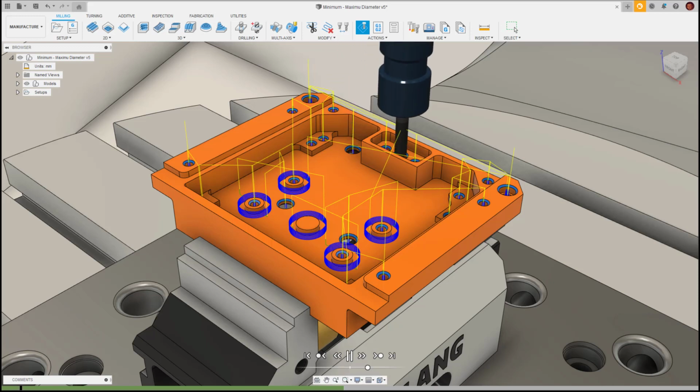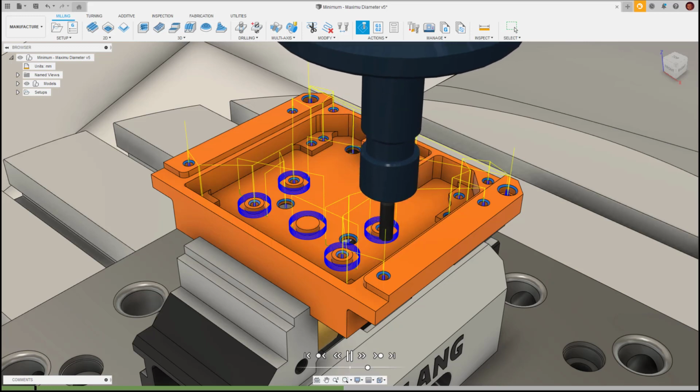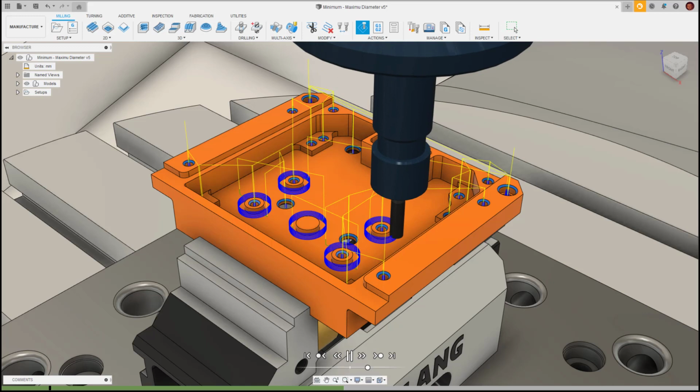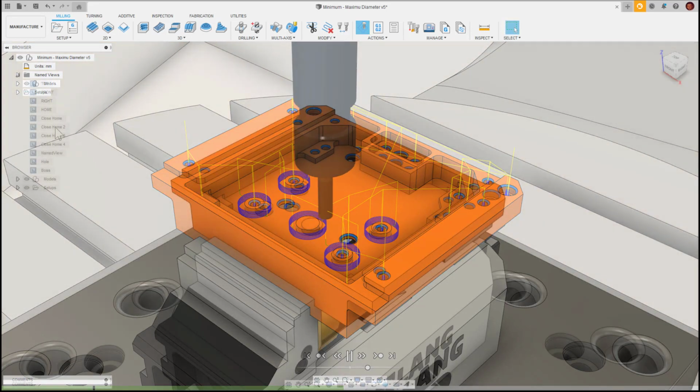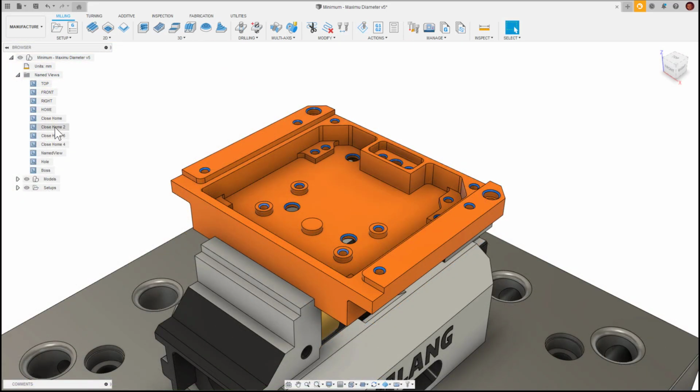In this release of Fusion360, we see a very exciting step forward for automation in Fusion360's manufacturing workspace, with the introduction of minimum and maximum diameter ranges for the toolpaths 2D bore, 2D circular and 2D thread, similar to what we see in the drilling toolpath. So how is this beneficial to you, the user?